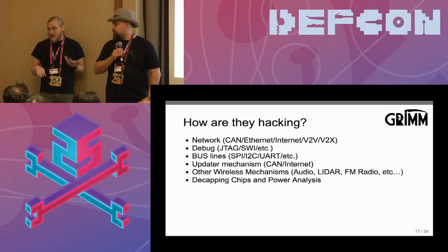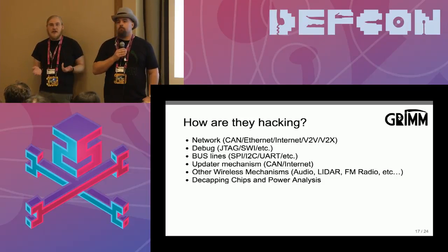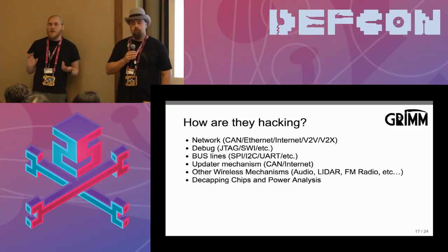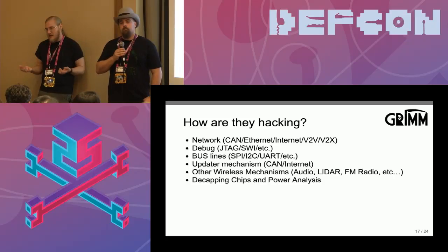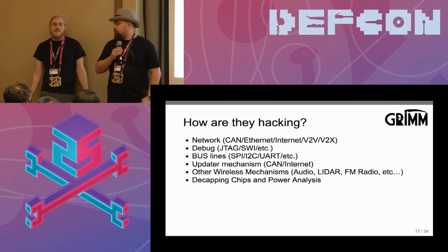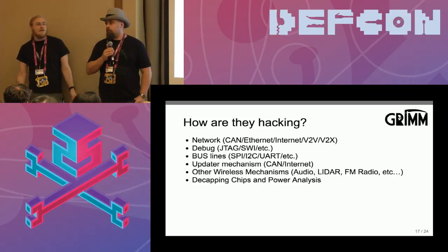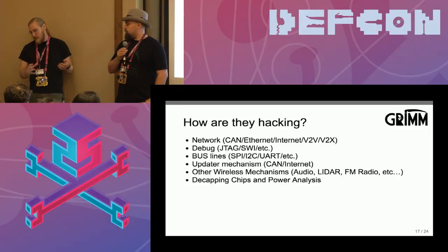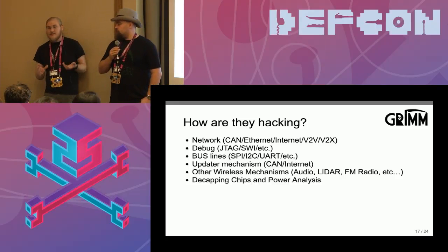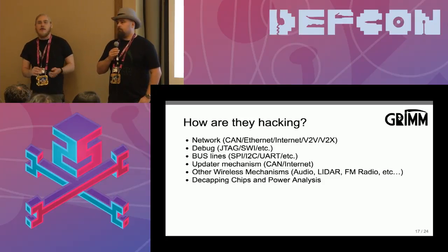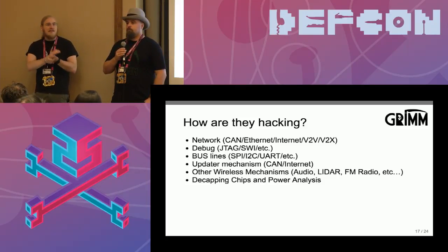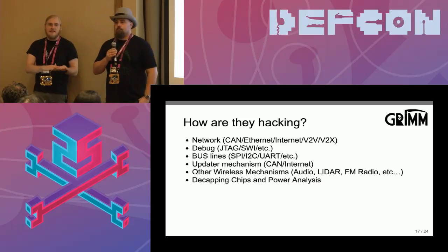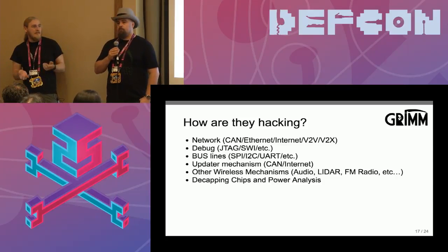Even if you don't have a debug peripheral, there's other buses you can attack. If you want to reverse engineer the operation of subcomponents, you've got SPI, I2C, and UARTs, which are commonly used to talk between modules on the same board. Firmware updates are less secure than you might hope. I don't think I've yet encountered a submodule other than head units that use code signing or any sort of decent integrity checking.